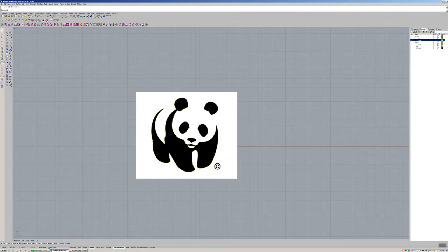And you're just going to left click it. And it says 11 curves joined into one closed curve. So again, Rhino communicates with you and it tells you what you got. If this says 11 curves joined into two open curves or something like that.